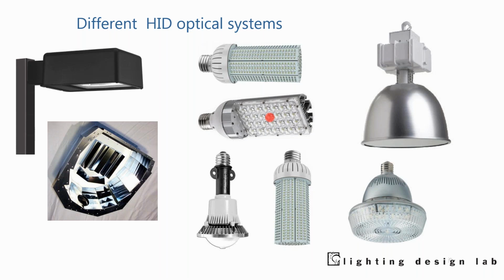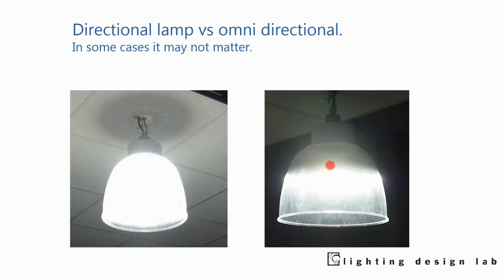One thing that you need to be aware of, if you do find one that you think could work, is what your reflector is like. If it's a translucent reflector or solid reflector. Especially if you go with a slightly directional one, you may have patterning that won't work. I know Costco is very concerned about the appearance of their high bay fixtures. They like that sparkle. They want it, and so this would not work for their purpose.